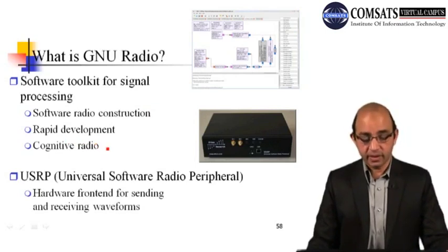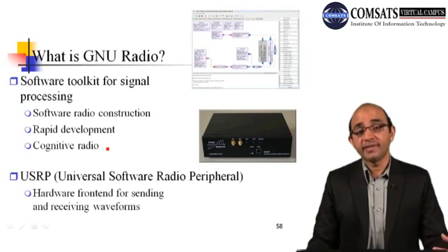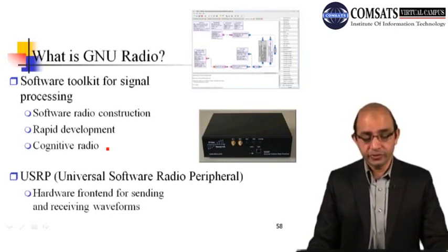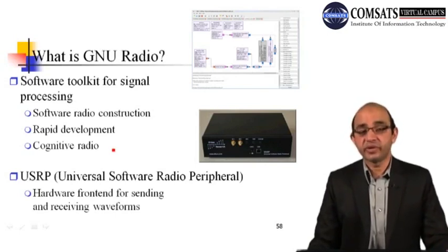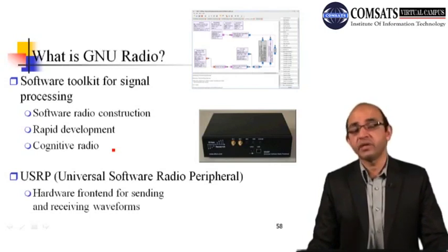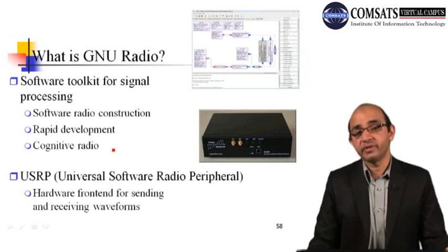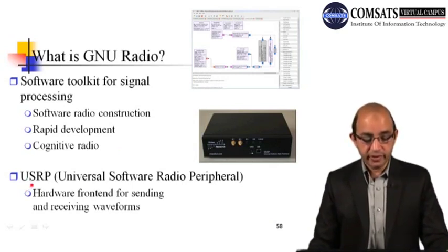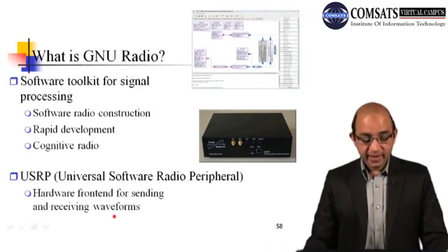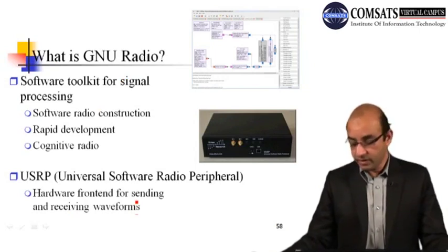We can construct cognitive radios, and there is specialized hardware that we can use in order to emulate and test our environment or our use case, maybe for wireless communication, or if we want to test some LTE protocol, or the communication that has to be performed by using GSM infrastructure. So we can use the Universal Software Radio Peripheral, that is the specialized hardware, together with this GNU Radio, that is software defined radio. It will be acting as a hardware front end for sending and receiving data waveforms.